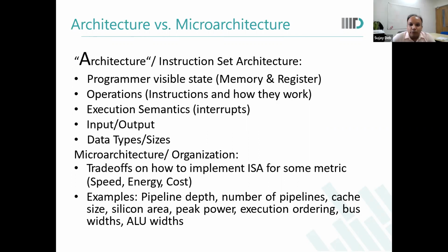Okay, so there are a few questions on the chat box. What programming language do you use in designing NoC? So see, ultimately you want an RTL, right? So you need that RTL for physically implementing that NoC. But for logically looking at how it will perform, to check different kinds of, let's say, routing and how it will impact your network performance, etc. For that there are simulators like NOCSIM written in C++. These are widely used.